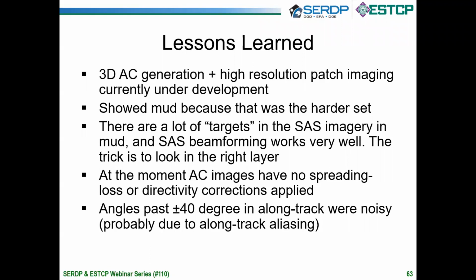The third bullet down is we're working on our beamforming, and we can do it. In fact, I forgot to mention, all the imaging that was previously done was just based on using the GPS coordinate location of the tow ship and then knowing what the payout was to the tow vehicle. That does not include any inertial navigation unit information from the tow body itself. As I previously said, the acoustic color hasn't removed any spreading loss or the directivity of the sources and receivers. But we think we're getting about plus or minus 40 degrees, so we can cover that 15-meter swath that we hope to cover.